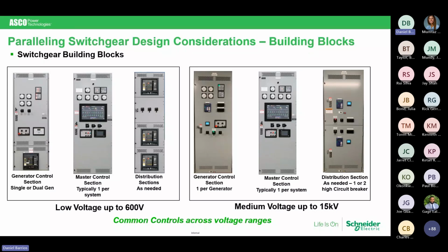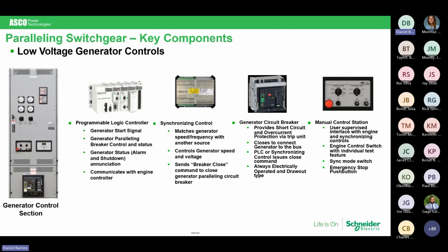We also manufacture that type of product also. We also can offer medium voltage transfer switches if you've never heard that or if you're curious. If you look on the left side, you notice that there can be potentially 3 to 4 breakers put into a distribution section with low voltage, 600 volt. When I move over to the 5 or 15 kV class, I am limited to 2 breakers, or I'm limited to 1 breaker and then housing the potential transformer or such in the upper section.